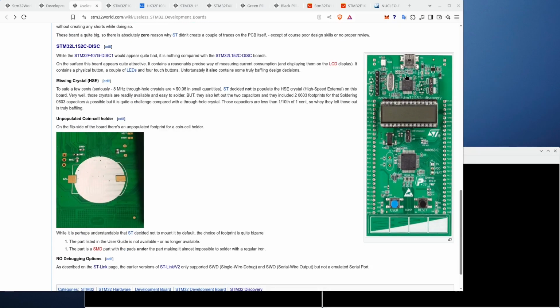Now, the ST-Link is connected. It doesn't have the serial communication, because this is only an ST-Link version 2. It doesn't have the virtual serial port, so that's not an option. But I could live with that if SWO was available, and SWO kind of is wired up to the SWO pin on the target MCU, which is pin PB3 if I'm not mistaken.